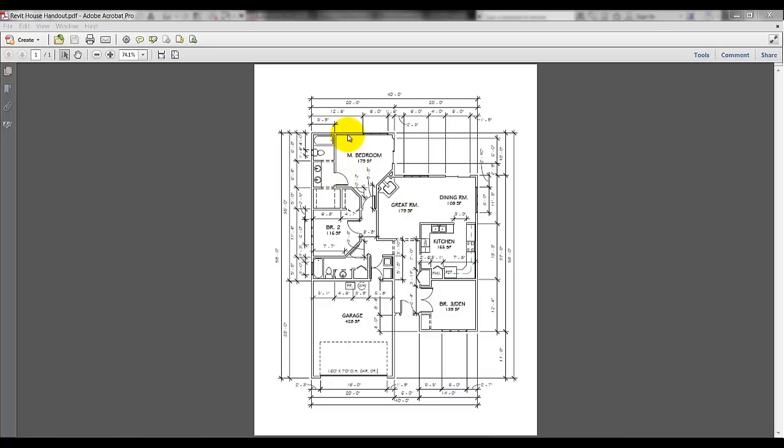Again, the walls are going to be 6-inch walls for the exterior or the perimeter of the plan, and they're going to be 4.5-inch interior walls for the interior walls that you'll see. The exception would be in the garage, where the inside walls of the garage are still the 6-inch generic walls, and you'll see that in a moment here when we get started in the walls section.